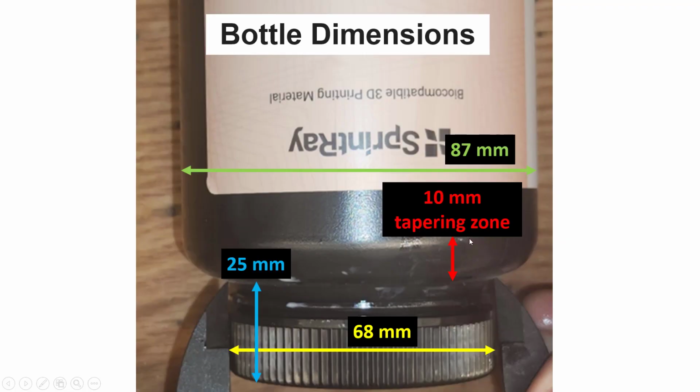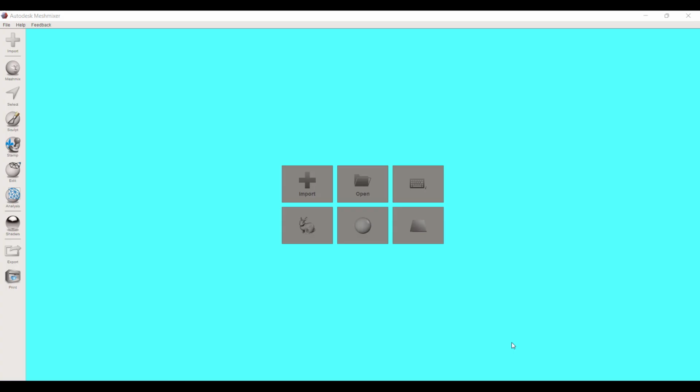So I'm rounding those up. We'll basically go with these measurements: 87 millimeter width, 25 millimeters up to right here where it's just purely cylindrical, and 68 millimeters wide. And then one additional measurement I went back and measured was, from right here where it goes from this cylindrical up to this area where it tapers out to the full bottle width, it's about a 10 millimeter tapering zone. All right, so with those dimensions, we should have everything we need now to go and start the design.